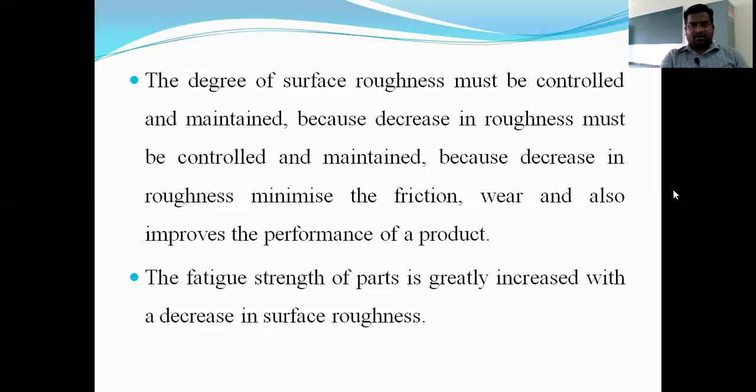If we are decreasing the surface roughness, we can minimize the friction and wear and also improve the performance of a product. The fatigue strength of parts is greatly increased with the decrease in surface roughness, right? Fatigue strength matters where we are applying continuous load. Where we are applying continuous load, the materials go under fatigue. The material which resists the fatigue has fatigue strength.